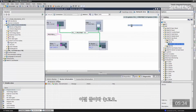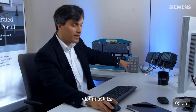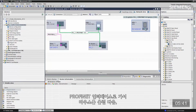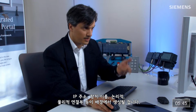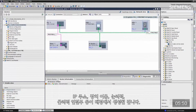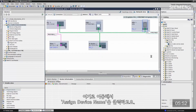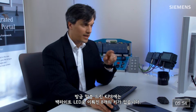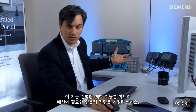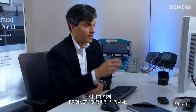Let's drag this on. So this is the Key Panel 8 that we're going to use in this project. Let me give focus and mouse over to its Profinet interface and drag it to the master module. Again, it's going to create the IP address, device name, and logical physical connections, everything in the background. Let's give focus to it and click on Assign Device Name. Just so you know, this KP8 does have these 8 keys with backlit LEDs, so we have complete control functionality through them, as well as associated inputs and outputs that we could wire. And it's treated as a Profinet I/O device.